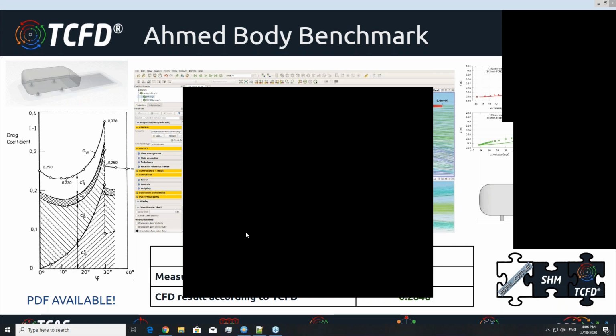Is there any opportunity to use CFTurbo for mean-line optimization of the geometry, for example, to do an initial sizing study of the machine to choose certain key diameters and passage depth dimensions, as well as to select the desired rotational speed? Yes, of course, because as I told you earlier, everything is parametric, and even some geometric results will be given by CFTurbo itself. So the answer is yes, absolutely.